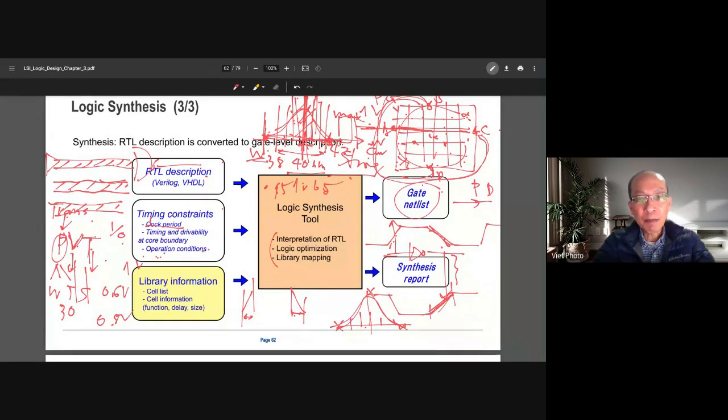The temperature can vary from minus 40 degrees C, and 25 C is typical. That's what we get in air conditioning. And then it goes to 155 degrees C, which is military grade. In commercial, it will be 125. But military requires 155, and minus 55. That's for military.